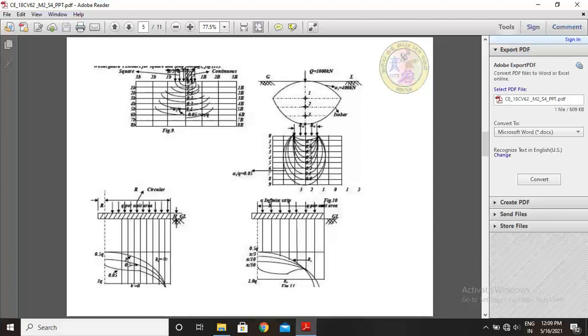We are considering breadth and depth with respect to the width of the footings, and we are applying the loads, that is continuous footings. So for the square footings, we are applying the loads continuously, and then stress occurs like that. See first curve, second curve, third curve, fourth. These curves are with respect to depth, at 0.6 meter, 0.5 meter, 0.4 meter, 0.3 meter, 0.2, like that.